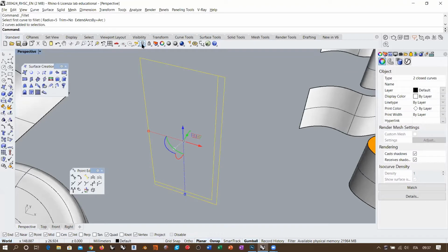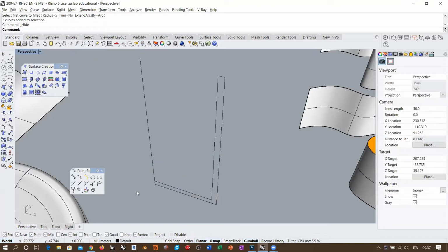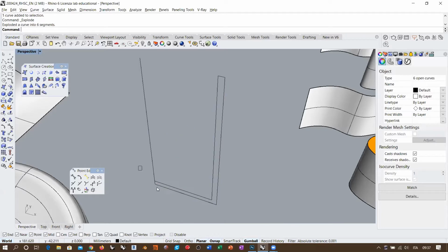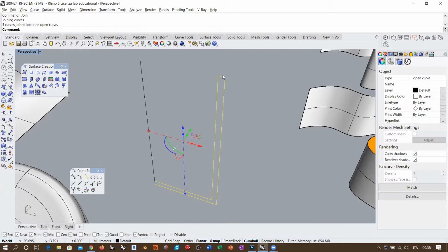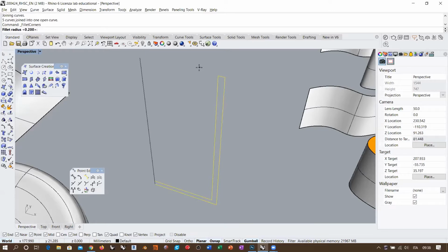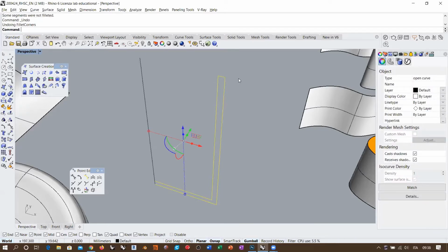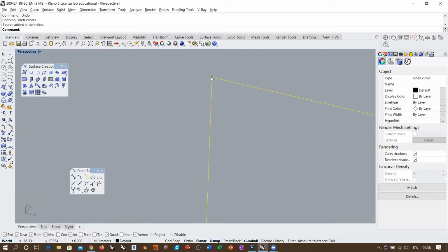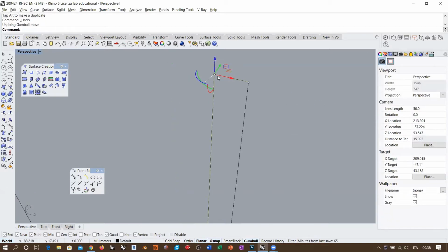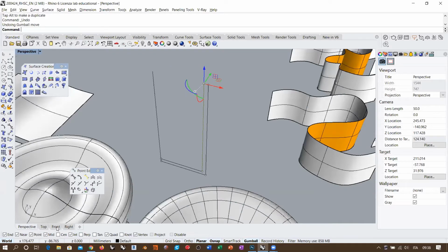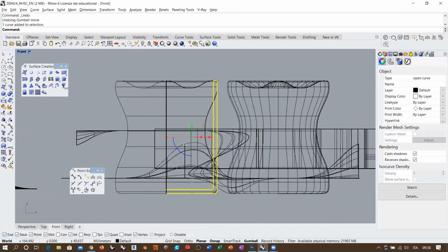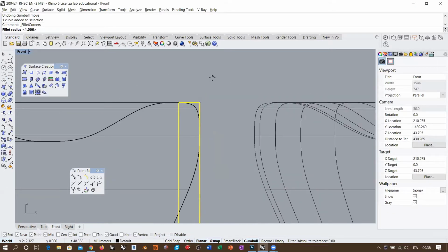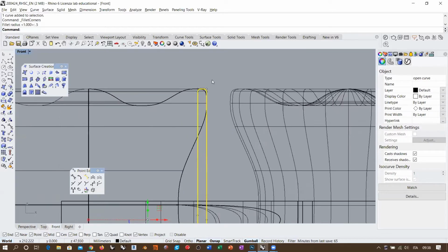Let me get rid of the 2 rectangles. And I could also, well, explode this curve because I don't need this side here. So it is open on the bottom. And then join this back together. And then eventually execute a fillet corners with, I don't know, a radius of 1. Oh, why is not filleting this? Eventually, this is weird. It should, but anyway, this is way quicker than any other process that we might want to realize. Oh, I think 1 is too much. Let's see if 0.5. Yeah, 0.5.